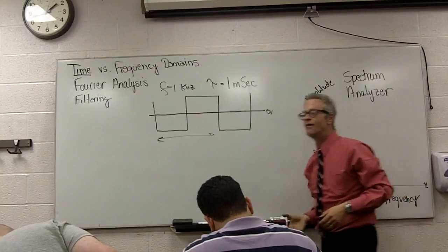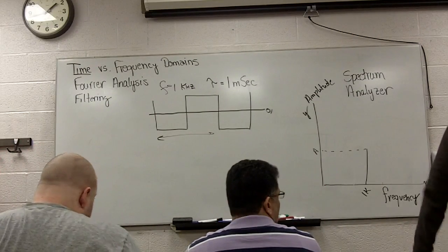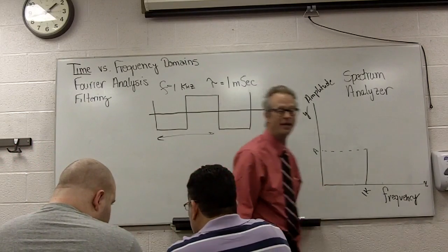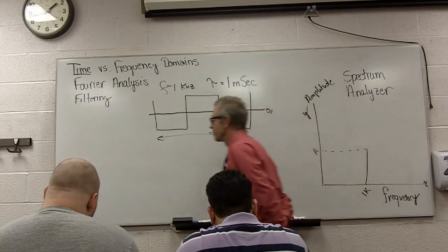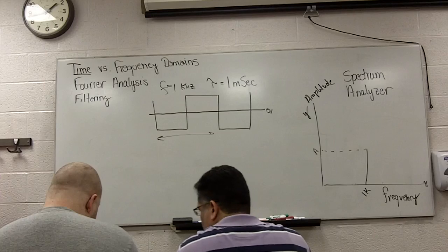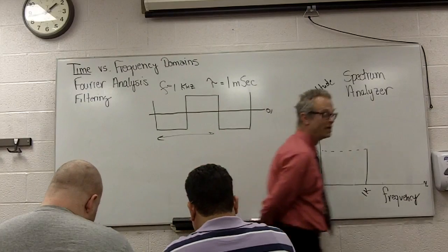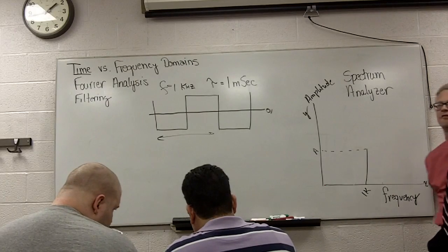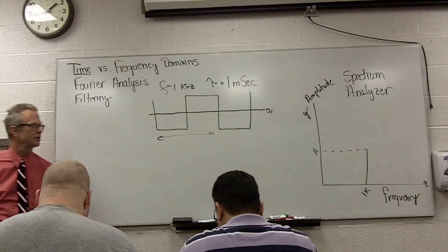So where did that square wave come from based on what we just said? Where did it come from based on what we just discussed about Mr. Fourier? A combination of sine waves. Okay? Do we have any idea what combination of sine waves would create that? And the answer is yes, we do. We can easily manufacture a square wave by adding sine waves together. And I'm going to show you how that works.